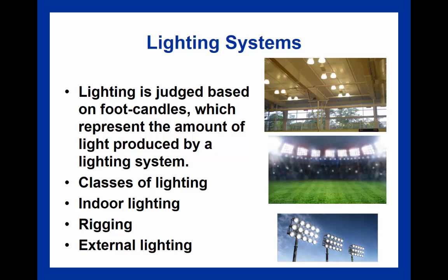So we need to make sure that the system is able to support what it's seeking to hang. So things like weight limits and forces and geometry, these are all important for facility managers to understand. Rigging strength can also be depleted or reduced by wear and tear and heat and then chemical exposure. So properly monitoring the rigging load is also important when we're talking about fighting reductions in load capacity.